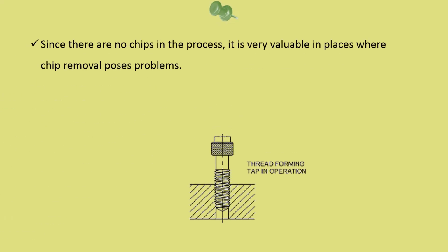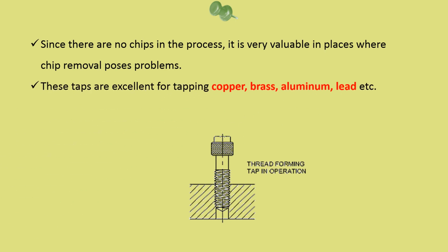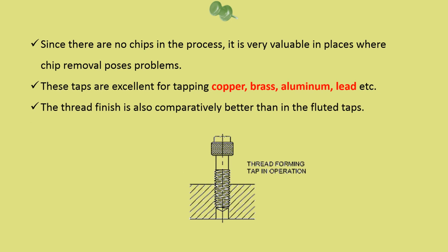Since there are no chips in the process, it is very valuable in places where chip removal poses problems. These taps are excellent for tapping copper, brass, aluminium, lead, etc. The thread finish is also comparatively better than with fluted taps.